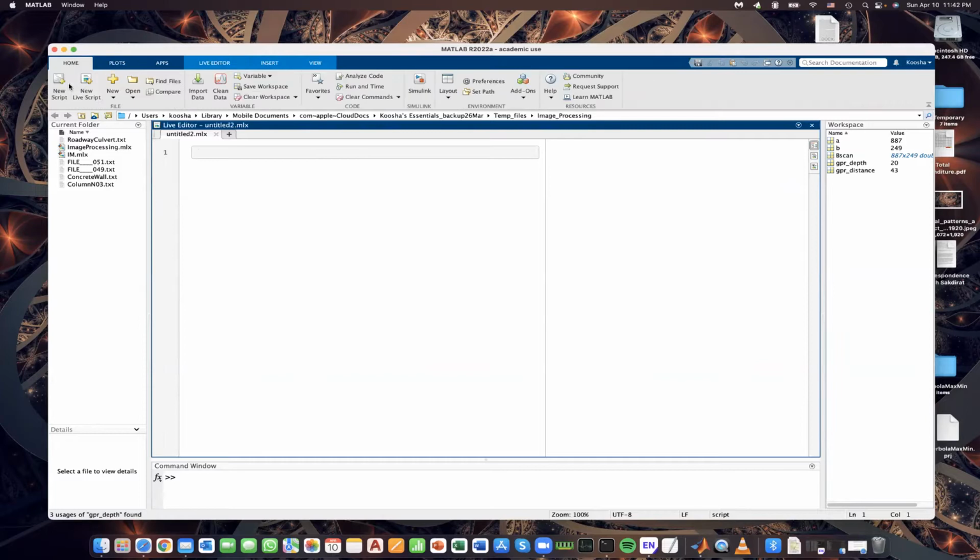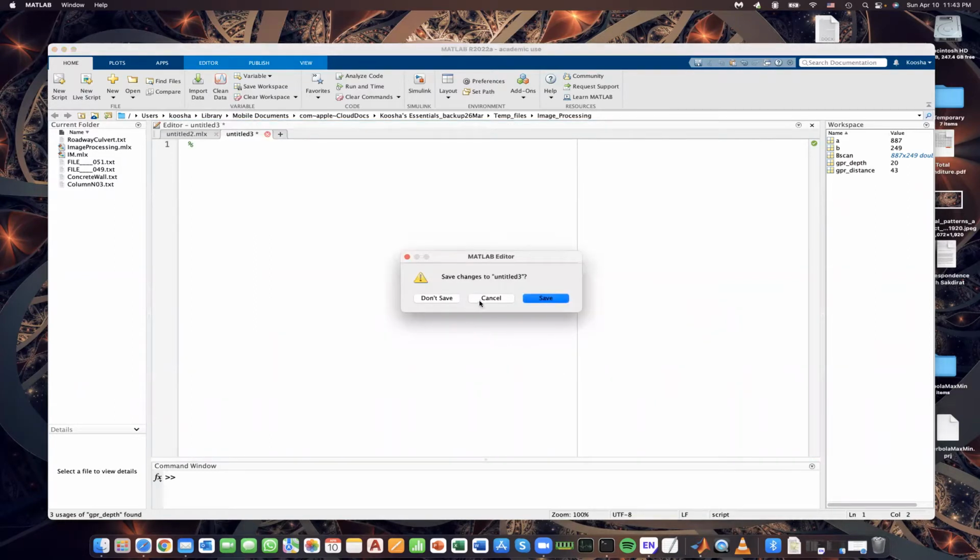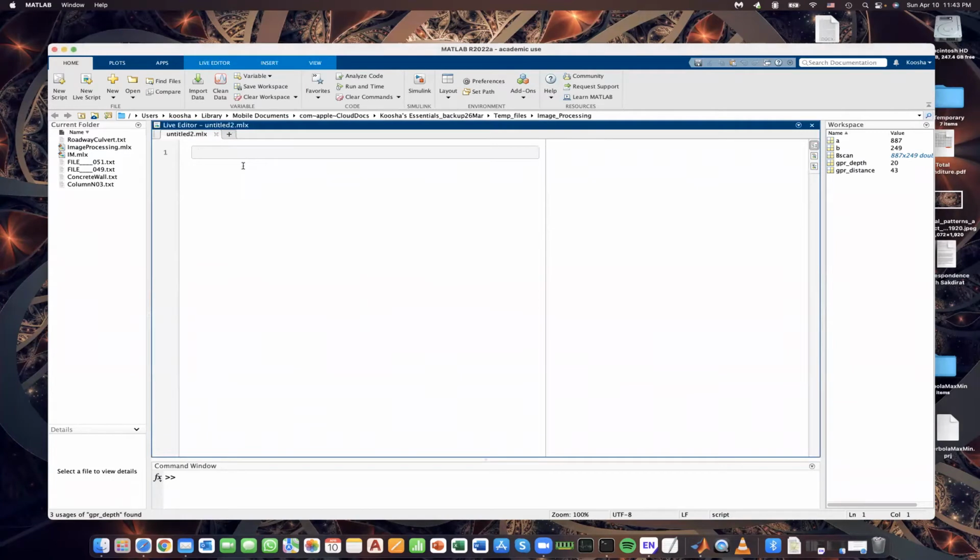Of course, there is an alternative here using two percentage signs. You can segmentize these different parts of the script so we can run them individually at a certain time. But for the sake of this course, let's work in a live script, because it is more comprehensive.